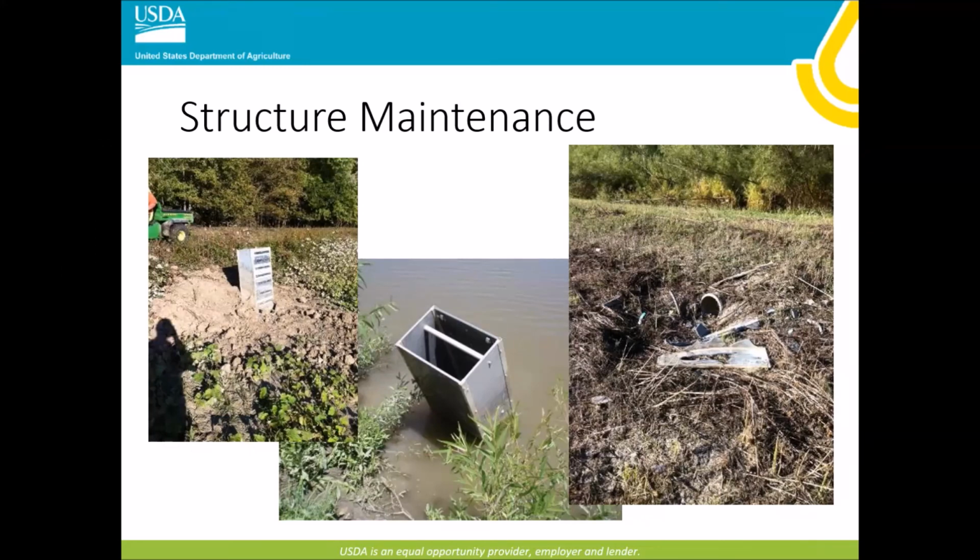I just can't promote enough that structures are very much a last resort in a wetland situation. One other thing I'd like to highlight from that center picture is the buoyant forces of plastic, once again. This structure is actually floating out of the ground because the pipe that it's connected to is floating. So be very careful with structures. Next slide.